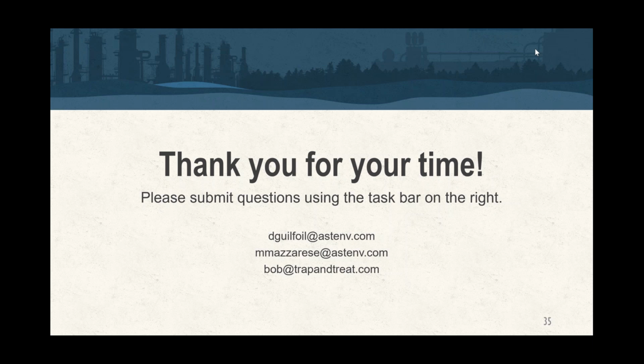Yeah, I'll just add something to Mike's comment related to the heterogeneity of these lithologies. That's the power of not being handcuffed with the amount of samples that you can collect. So if you're within a 2-foot zone of soil and you see a change in lithology and a high PID reading, even though we just give recommendations of samples every 1 to 2 vertical feet, you as the practitioner can collect as many as you want in order to build that conceptual site model. You have the power to do that because you're not handcuffed with the number of samples that you can collect. So the more samples, the better.